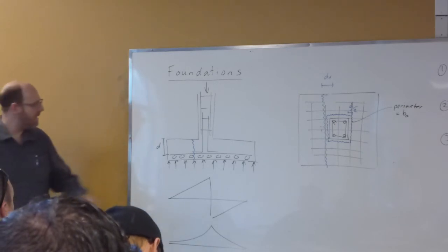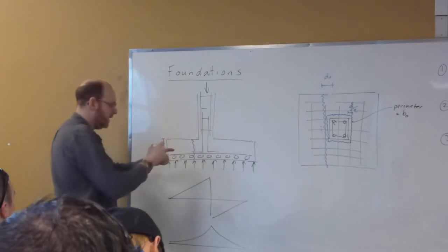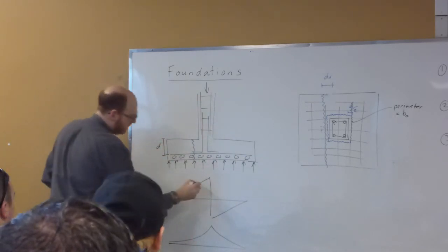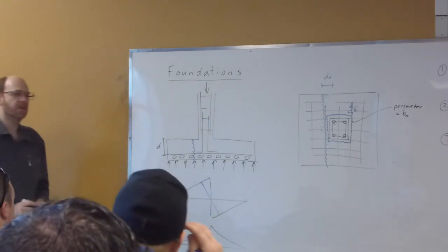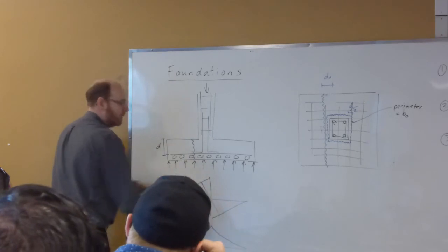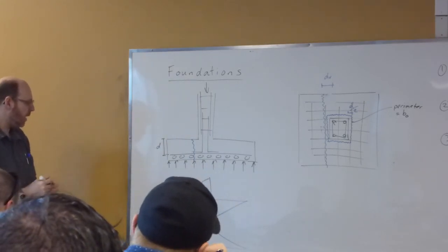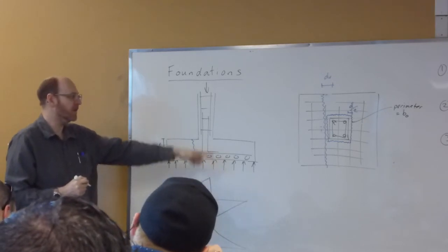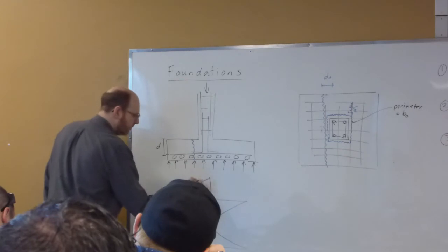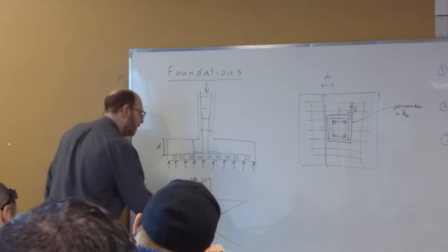Now, technically, the way I've drawn this is with a point load applied right in the middle. Physically, there is some size associated with it, so more appropriate is something like that, where it goes up the column face and then varies across the width of the column itself. But again, what we're interested in is not calculating this maximum value, at least for our one-way shear. We're calculating that at a distance of dV. So here's our column face, and we want to find our VF out here.